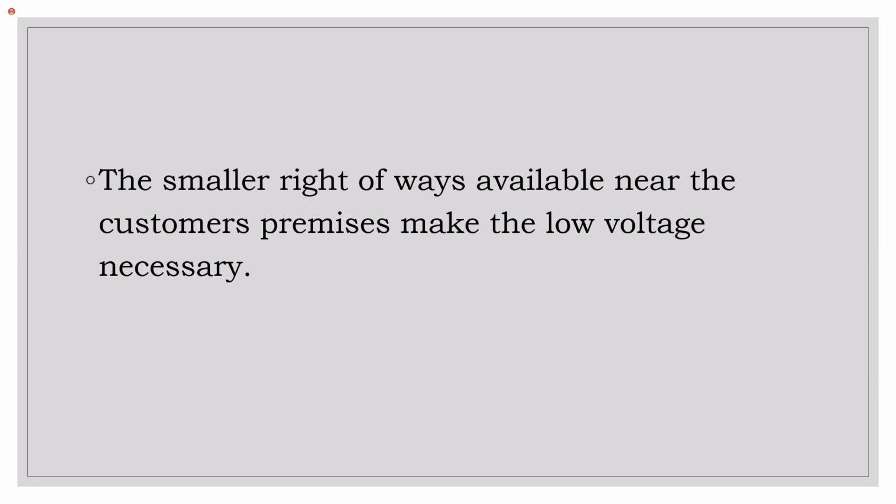All right. But within a residential community, what is on the pole is 24 kilovolts, and we are good with that. Of course, you can have your spurs, which are your 3-phase 415s, going down a little lane. You're not going to carry the 24 down that little lane just for those few houses.